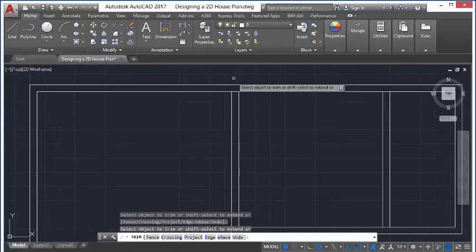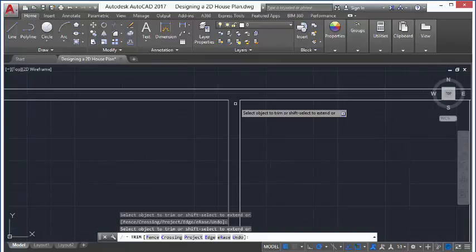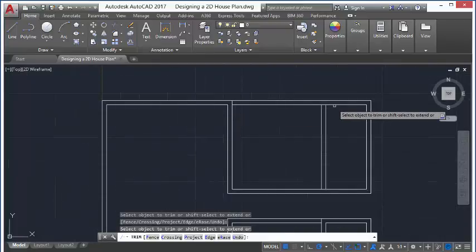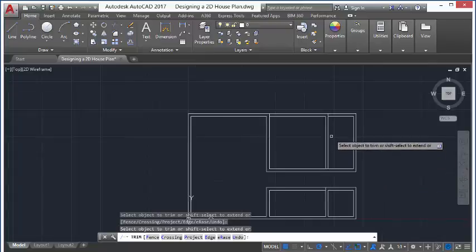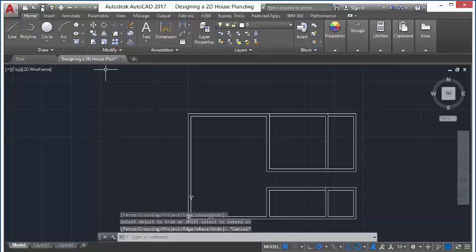Push the mouse forward to zoom in. Clean up this area. Shift and extend. I'm still in the zoom mode and doing all these things. Extend, clean up, press escape, click save. It's a standard practice to save your drawing very often.